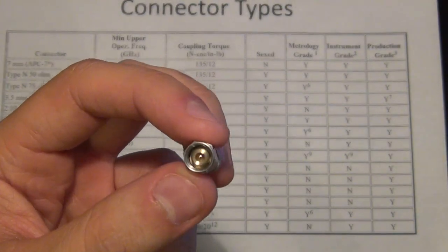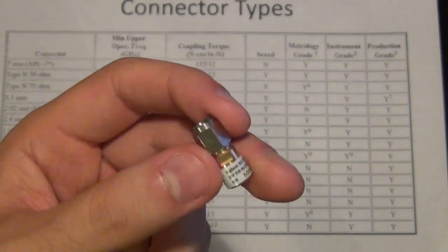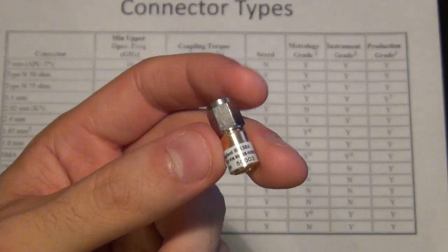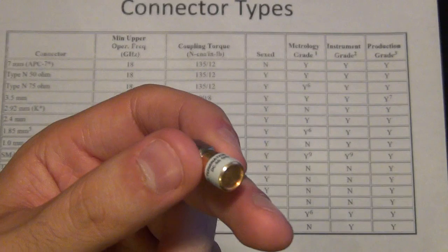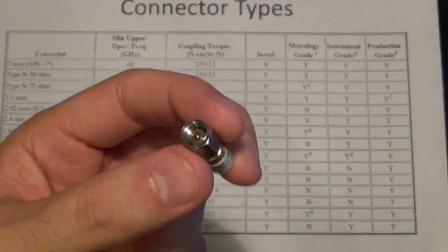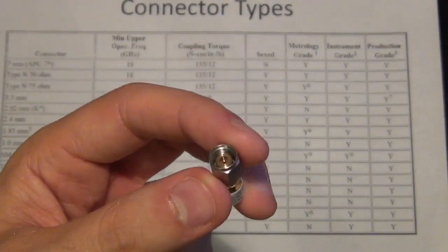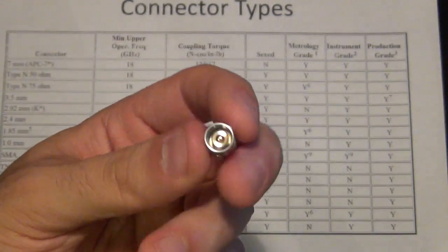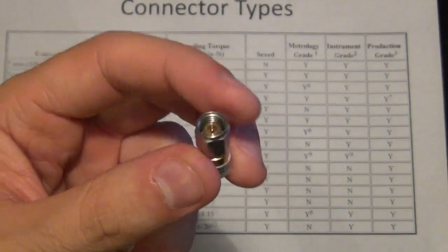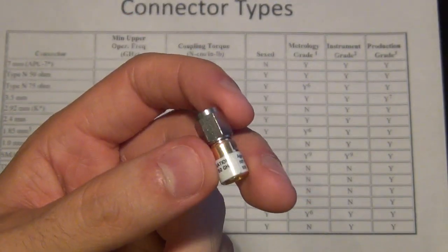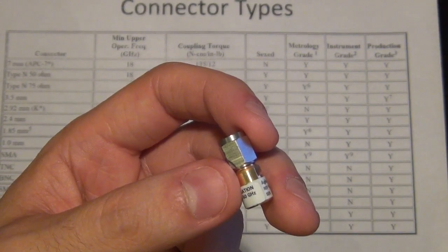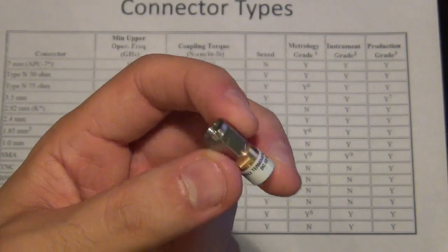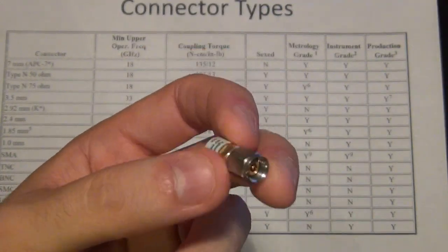And when you use this, make sure that you don't put too much current through them. These are not designed to accept a lot of DC current. Also, there's a maximum power you can put into these before you heat up the resistor too much and you break it and it won't be 50 ohm anymore. So you have to be very cautious with these. Terminations are really widely used when you have, for example, a differential circuit and you want to terminate one output of your differential circuit while you measure the other one. So these things are used all the time for those purposes.